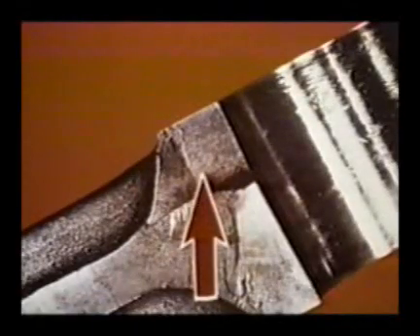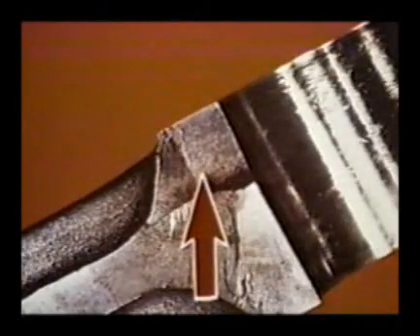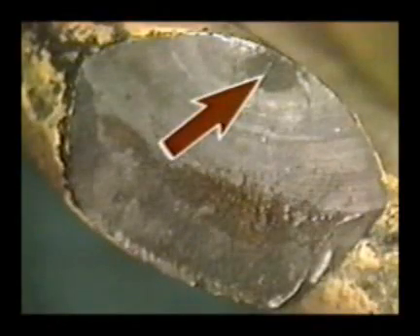Pre-cracks can sometimes be identified by dark forging scale or temper oxides inside the crack. This indicates the crack existed during heat treat, a possible forging lap or quench crack. Sometimes a pre-crack has paint, rust, or oxides on its surface, good evidence that the crack existed before the part was placed in service. For example, the pre-crack in this part has a dark stain, suggesting it occurred during manufacturing. Ratchet marks and beach marks start at the bottom of the stained area.